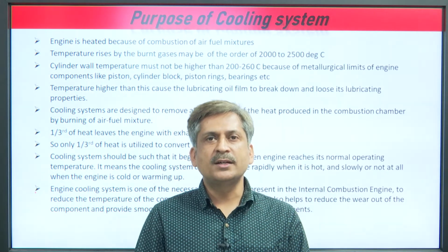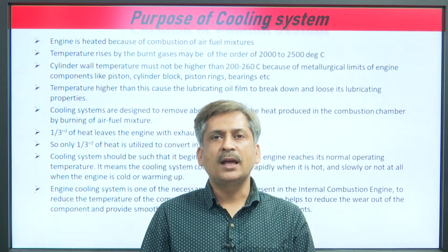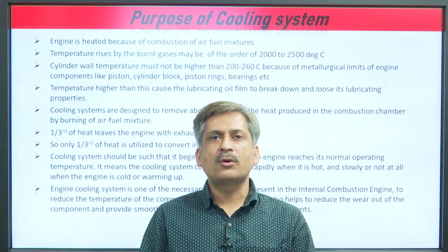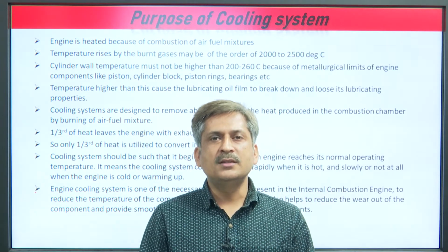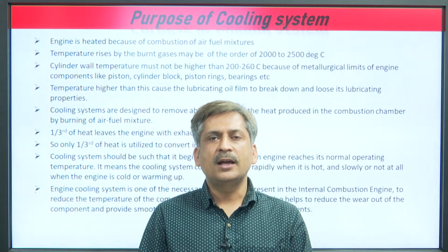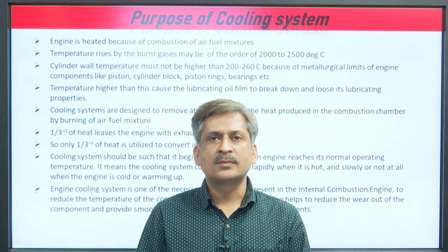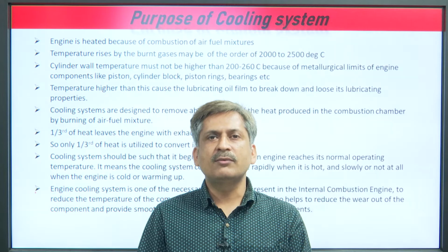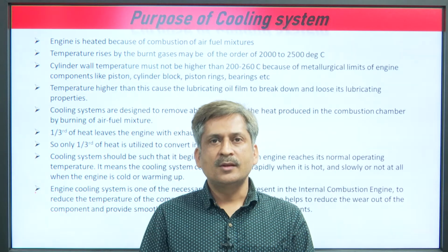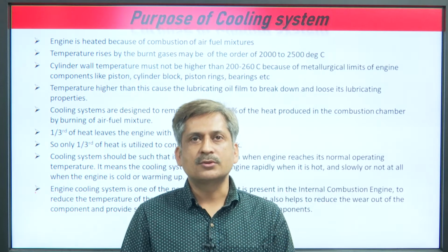If you approximate, 1/3 of the chemical energy of the fuel is removed by the engine cooling system. This is only an approximation. 1/3 means 30 to 35% is lost, and 30 to 35% is lost in the exhaust with the exhaust flue gases. So the remaining approximately 30 to 35% is only convertible into useful work, which is known as its thermal efficiency, maybe the brake thermal efficiency also.